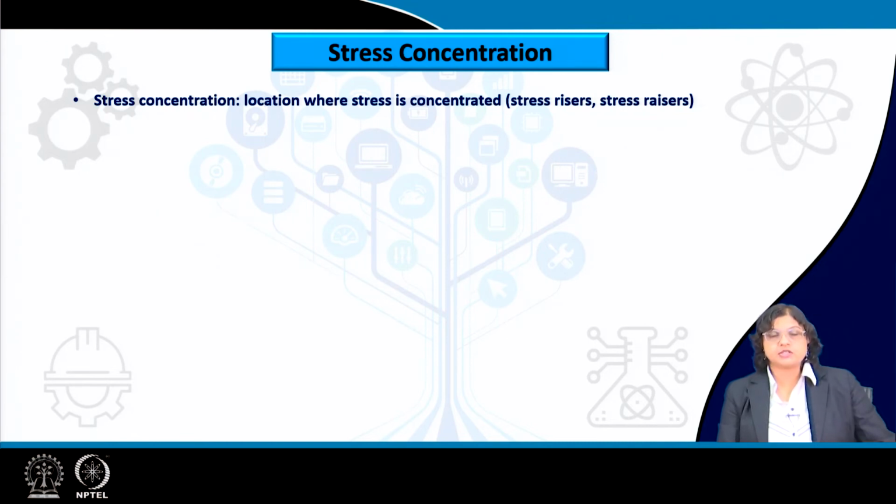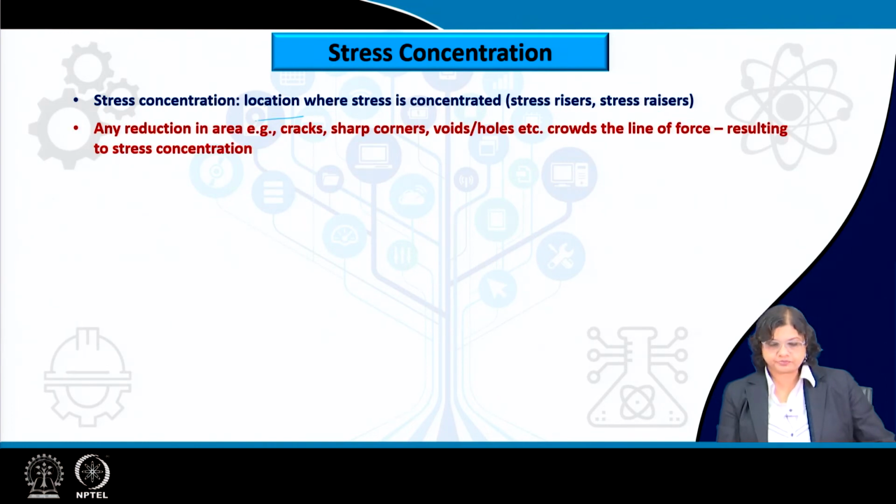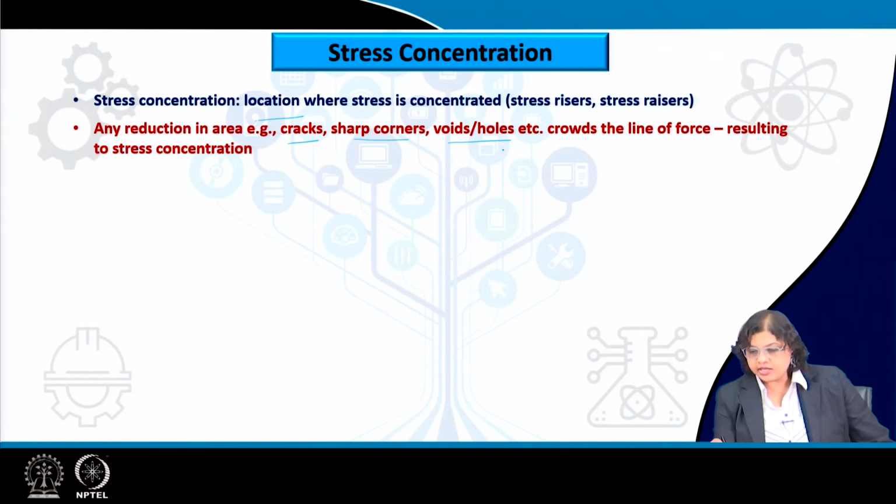If we are applying stress, the stress is actually not evenly distributed; rather, it will be concentrated at those locations, which can be considered as stress risers or stress raisers, which increase the amount of stress. Any reduction in area could be due to the presence of cracks, but not limited to that. It could also be because of sharp corners, voids or holes as per the design of the component. Any such non-uniformity in the structure leads to crowding in the line of force,